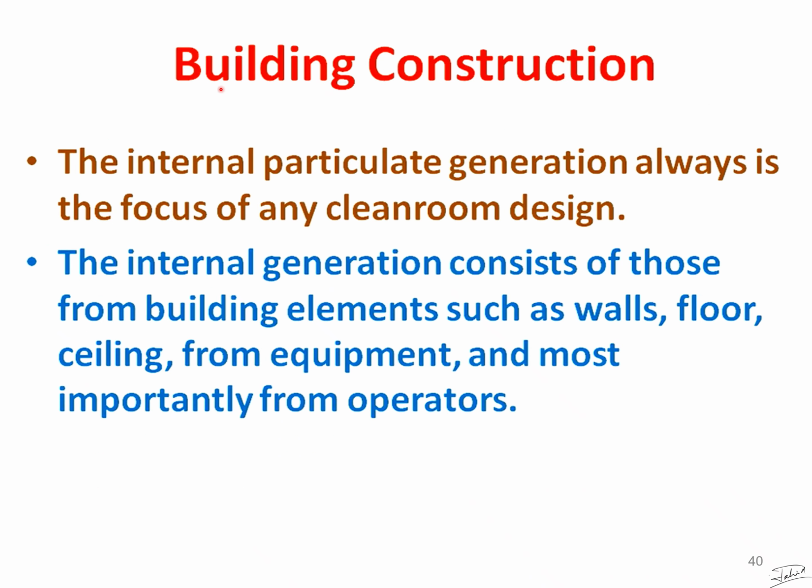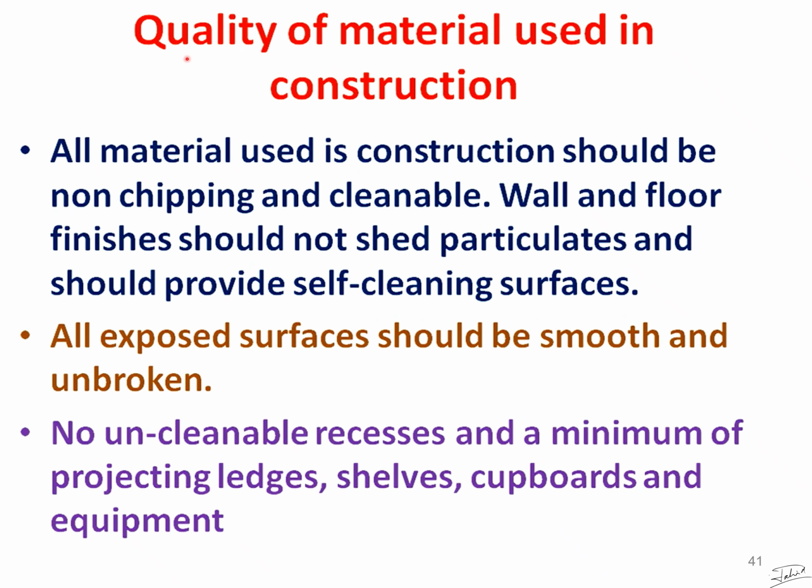Now let's see the building construction, how we would construct for this HVAC system. The internal particulate generation is always the focus of any clean room design. The internal generation consists of those from building elements such as wall, floor, ceiling, equipment, and most importantly from operators. So what should be the quality of material used in construction? All material used in construction should be non-chipping and cleanable. Wall and floor finishes should not shed particulates and should provide self-cleaning surfaces.